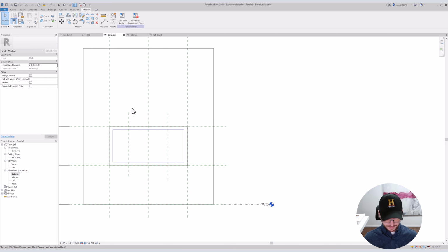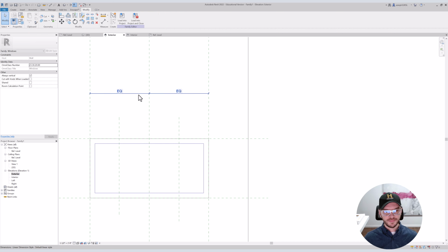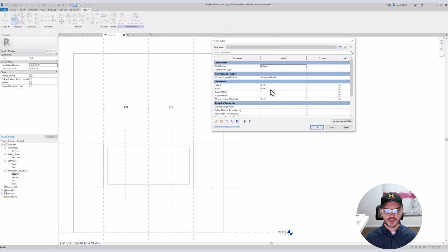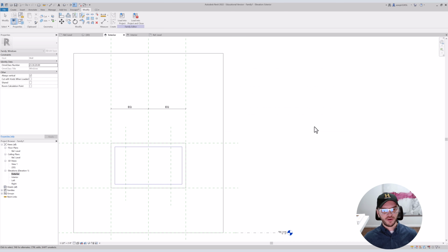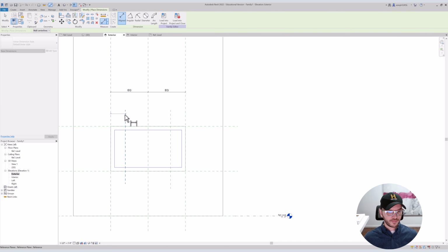Either way is fine. But what we are going to do, here we go. This is what I want to do. This we can set to equal. All right. Let's make sure that this dimension doesn't break. And by break, I mean no errors after we've flexed this. Flexing is just stretching and doing whatever you want with it just to test it. So nothing broke, right? Let's continue.